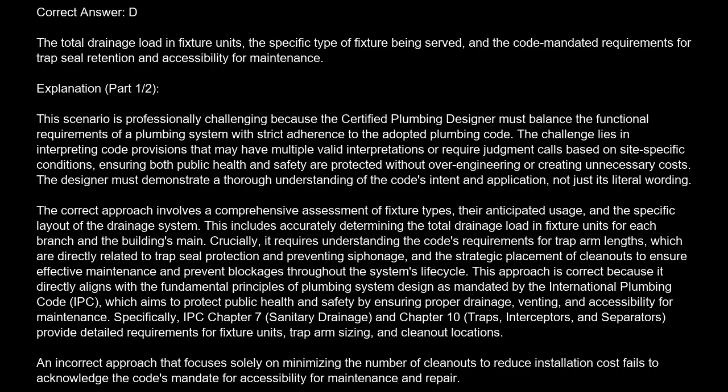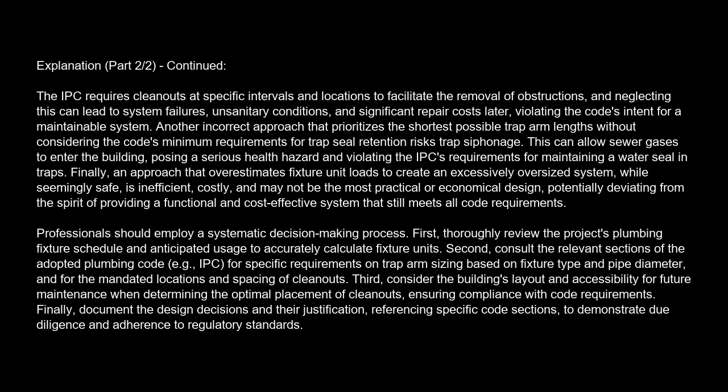An incorrect approach that focuses solely on minimizing the number of cleanouts to reduce installation cost fails to acknowledge the code's mandate for accessibility for maintenance and repair. The IPC requires cleanouts at specific intervals and locations to facilitate the removal of obstructions, and neglecting this can lead to system failures, unsanitary conditions, and significant repair costs later, violating the code's intent for a maintainable system.